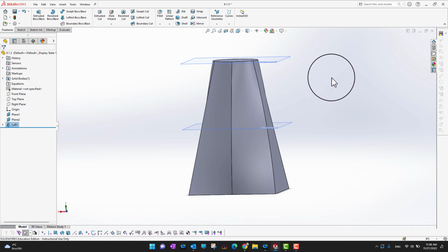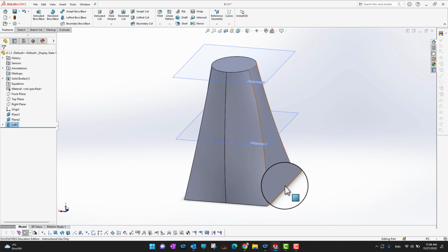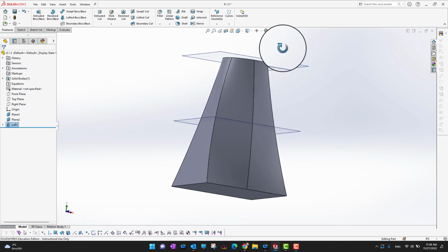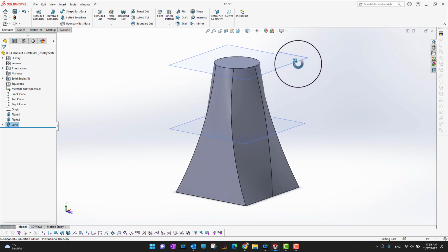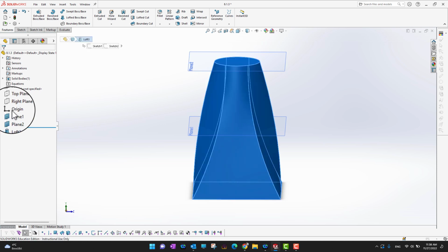Okay, look, in this way I can just use the loft command for multiple sketches, from the first sketch to the second, and from the second to the third, and in that way you can make whatever kind of drawing or model you want to make. But there is another thing which I want to mention here. So let's go and edit the feature.